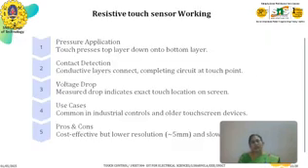The working of the resistive touch sensor starts with pressure application. The pressure is applied on the top layer down onto the bottom layer. Through this pressure, the conductive layers connect, completing the circuit at the touch point. From this, changes in the voltage drop occur, and from the measurement of the voltage drop we can calculate the exact position of the touch point.